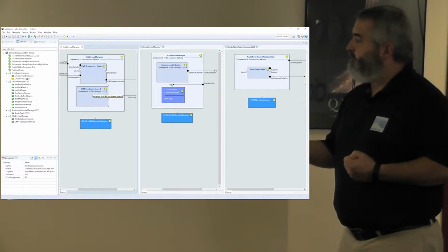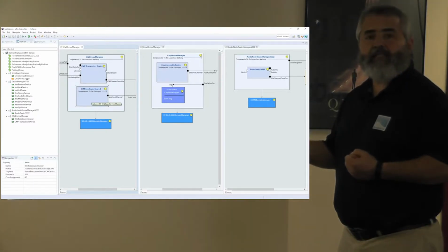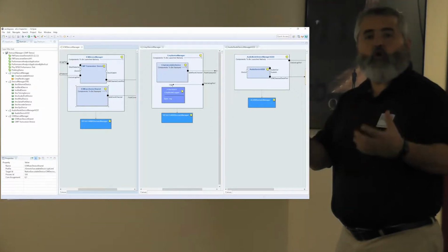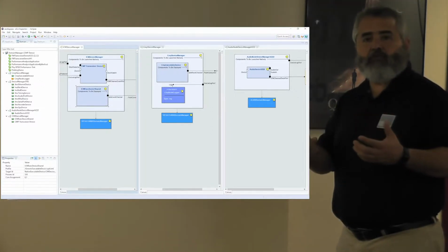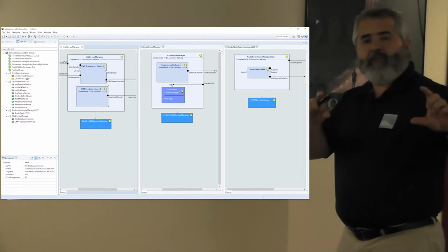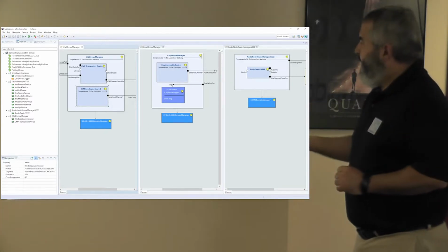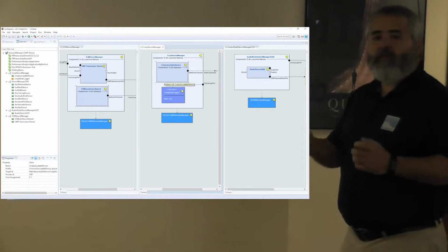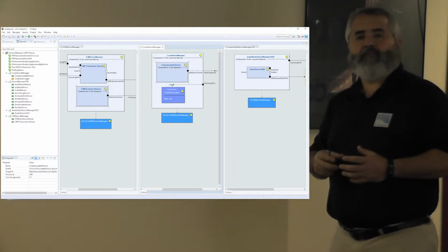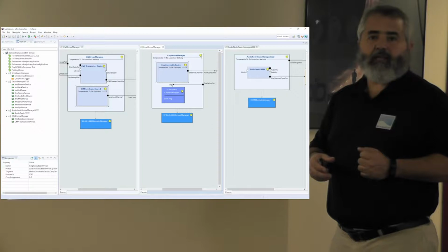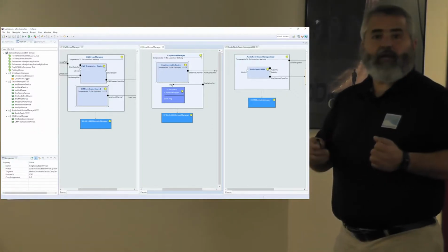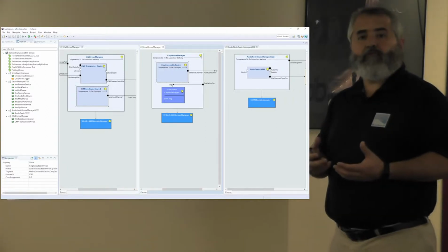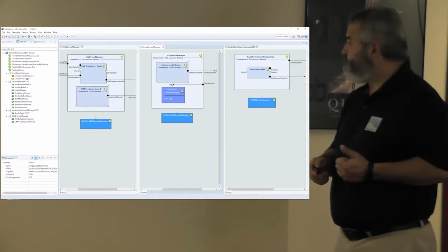And the second light blue box is a small ARM that allows me to do some processing, some execution of software within the same board. In the middle, we have a second board. This one has an i7, an x86 running Linux, that will be able to host my waveform application and execute it.